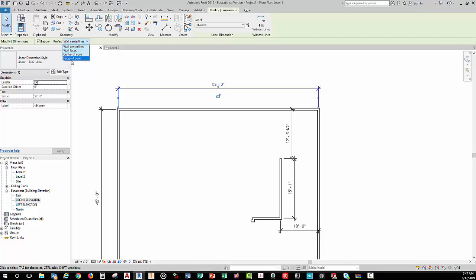And what that is, it's like, you know, if you're measuring from one wall to another wall, like the bottom plate of one wall to the bottom plate of another wall, then if I was building that, I would want to know where the edge of that stud is, or the edge of my structural member. So I'm going to dimension from stud to stud, which would be faces of core. And later on I'll show you how to work with the walls and adjust them differently.